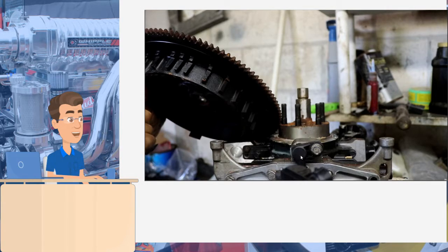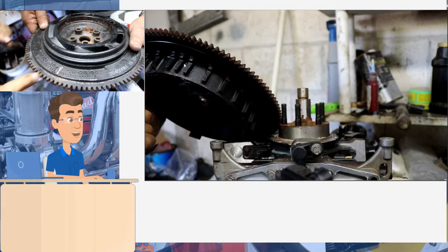Because you remember the crankshaft position sensor works with a magnetic signal. If you have the separation of those teeth equal, and suddenly you have in between two of them one element in between, this is the zero position. Right now I am going to explain.